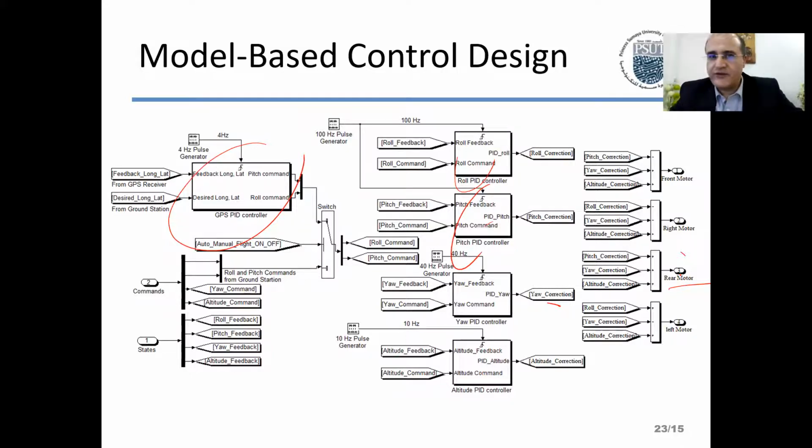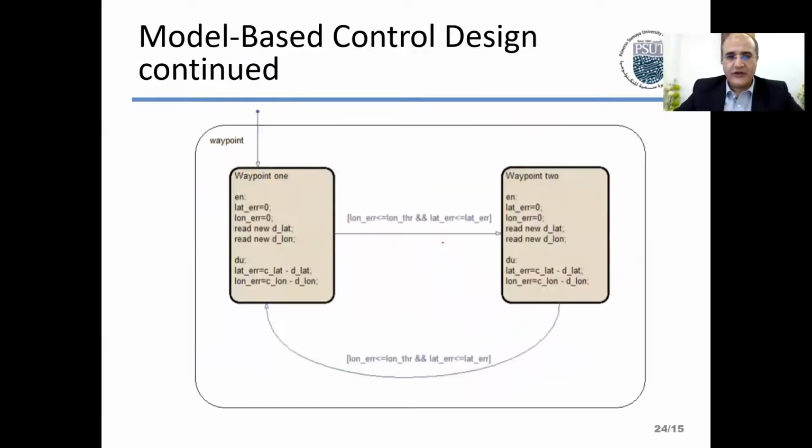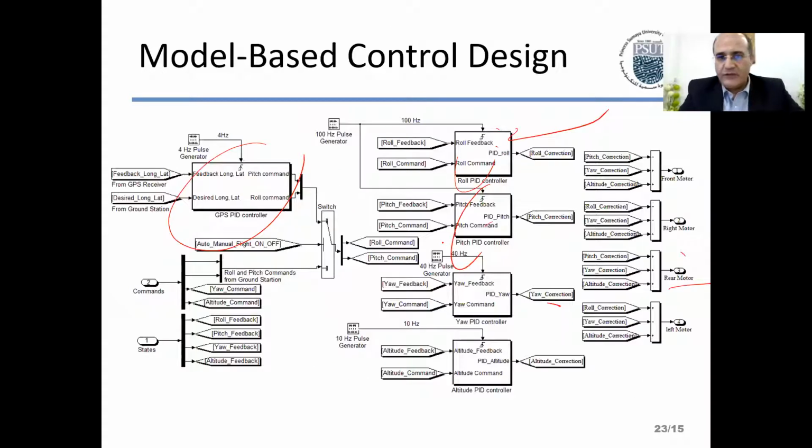real timeness of things. So here you're telling that this piece, double click on this, you'll find some code. You're gonna find this PID controller by double clicking here. But here on the high level, what's in here has to be executed within 100 hertz frequency, 100 times in a second, right?